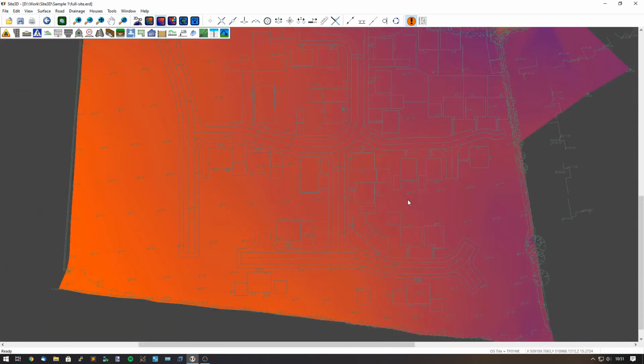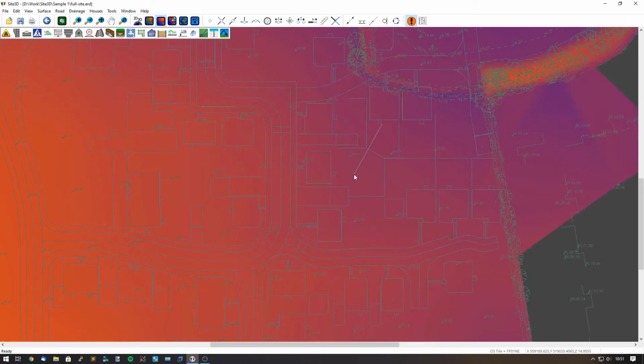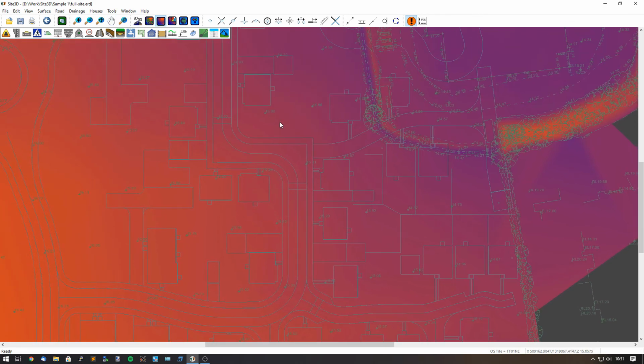You can also then see, as you're going in between buildings, what's going to happen with the garden path. So you can see this area here is flowing towards the building, and so is that one. These would be areas where you might want to reconsider the levels of the FFLs and the garden plot levels and things like that, to stop water flowing directly towards the back of a house or something like that. And you get the choice to see exactly which direction the water would flow in.